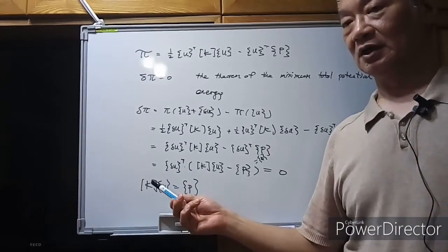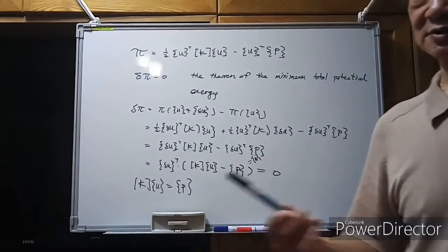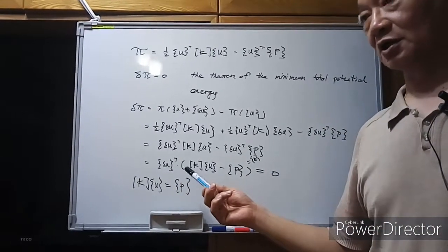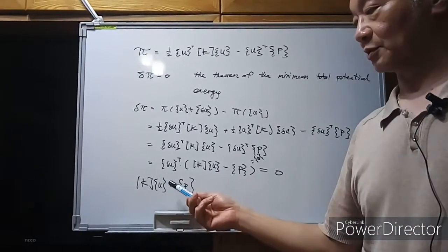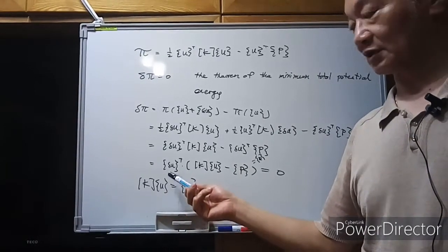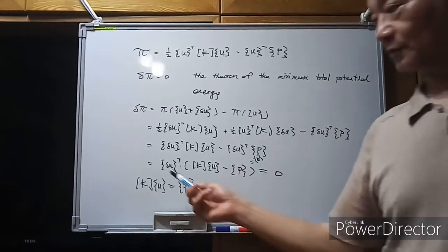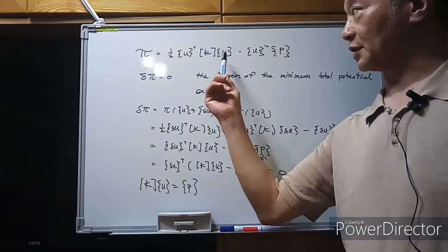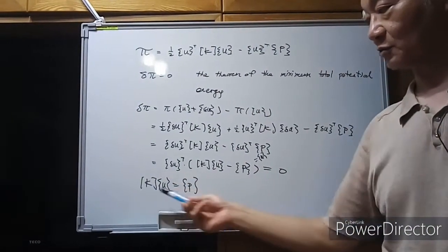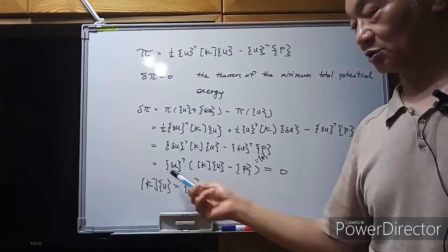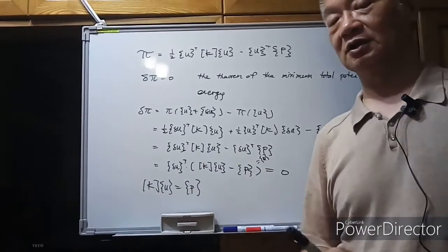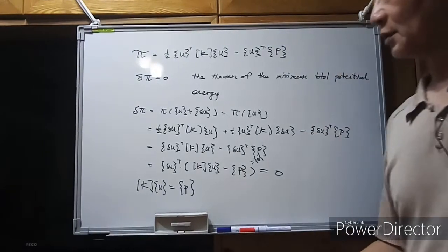You can use an existing package which uses the Gaussian elimination method to help you get the unknown U vector. So after we calculate the K matrix and get the P vector, the next thing we need to do is solve the simultaneous equations to get the U vector.